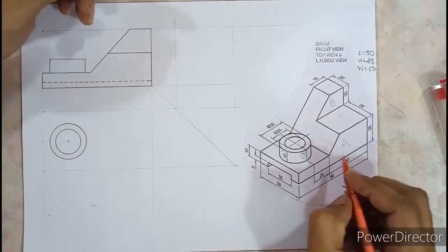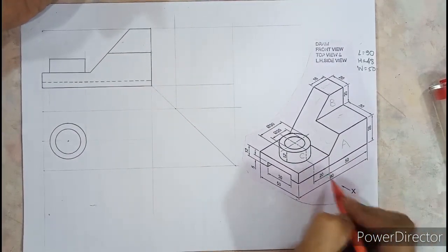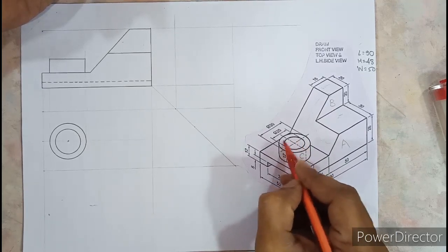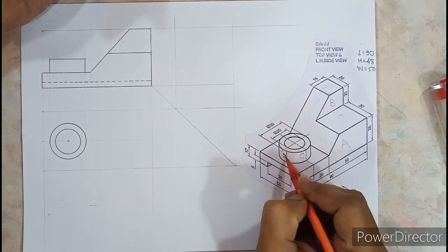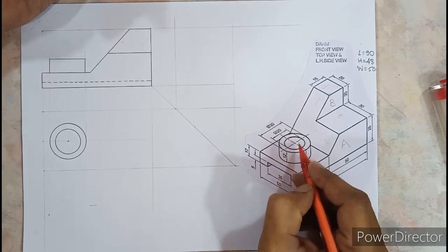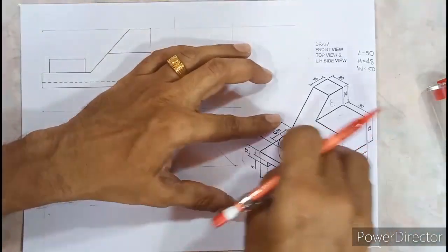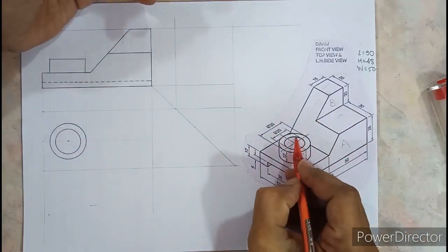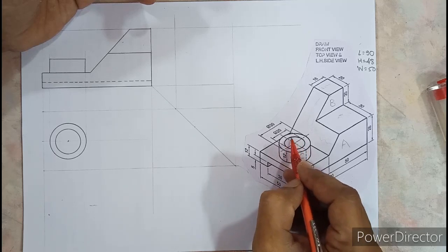Okay, now there's one more thing left in the front view. The last thing what is left is, in the front view, you cannot see this circular cavity which is going inside. By mistake, students assume that the depth of the cavity is 12. See, if the depth of the cavity was 12, you could have seen the inner edge, right? But it is not so. So again I repeat, whenever the depth of a cavity is not mentioned, you have to assume that it is throughout.